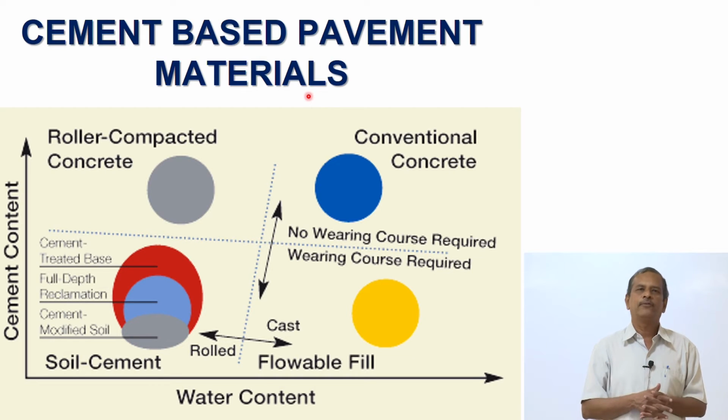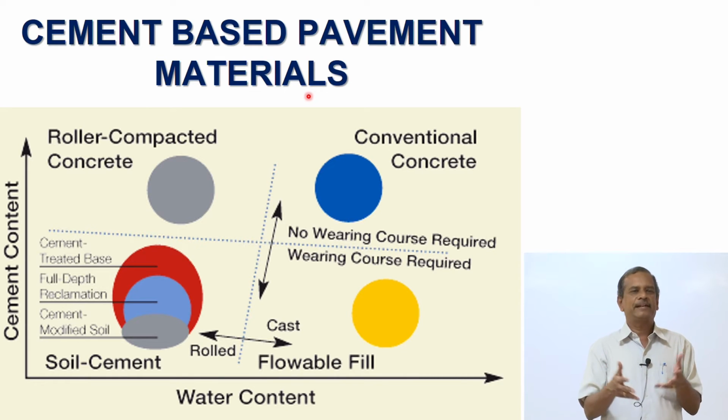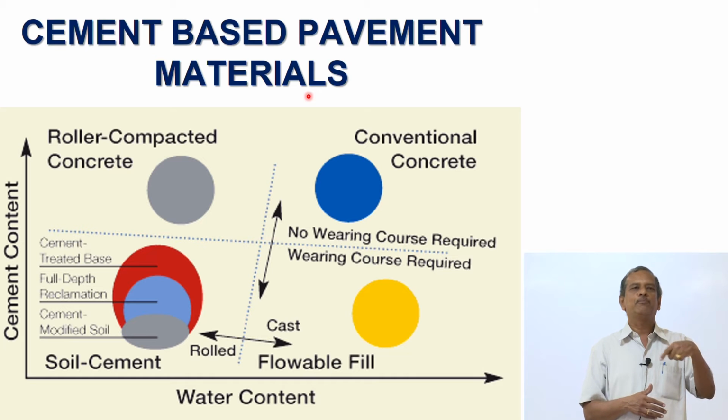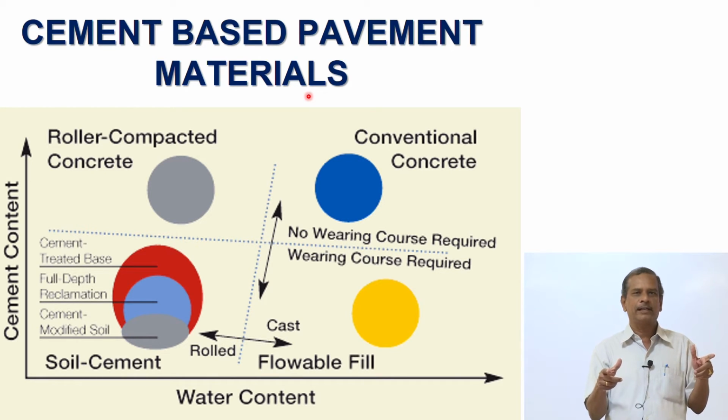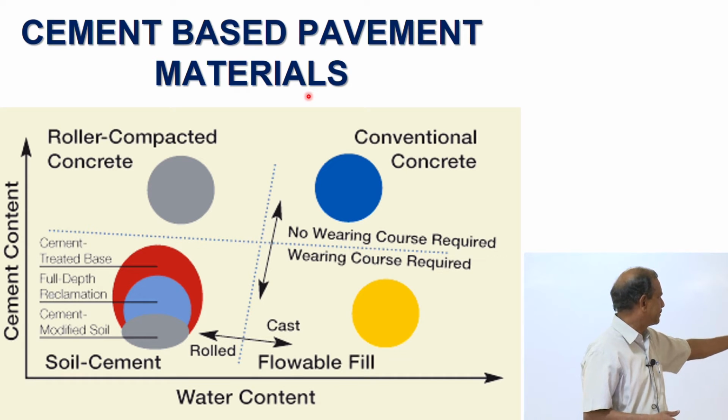One way of reducing the aggregate consumption is that you can introduce cement. What I am talking about is that if the subgrade is weak, as I was mentioning, with a CBR of the subgrade of 2%, 3%, can I improve the strength of the subgrade soil? Yes, you can do that. I can add cement to the soil. I can add lime to the soil. I am trying to modify the properties of the soil, reduce the plasticity, and reduce moisture-induced damage. So if I can improve the strength of the subgrade soil by stabilization, then I can use cement. That is called soil cement layers.